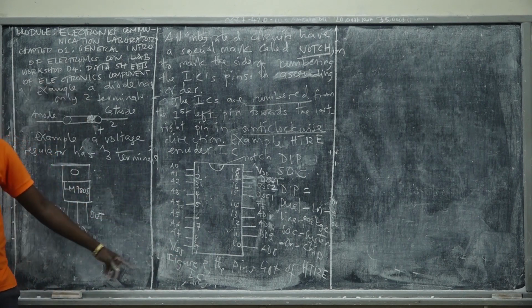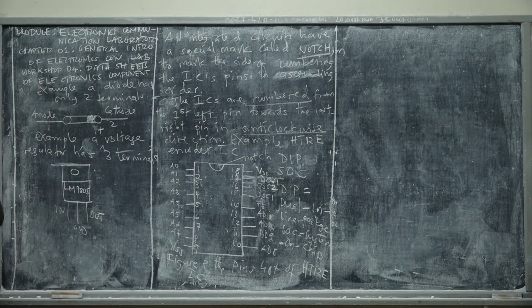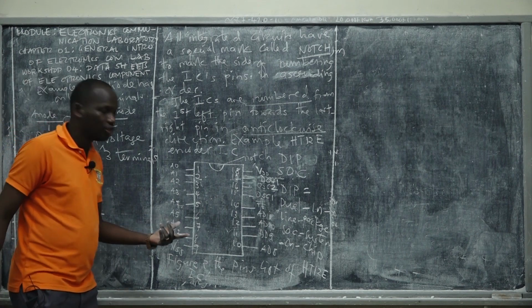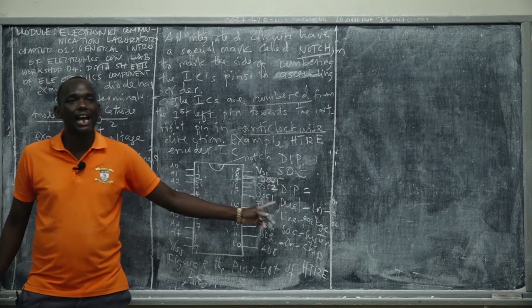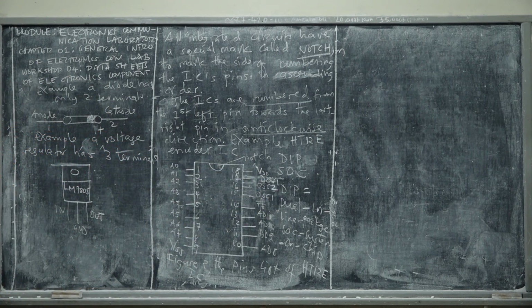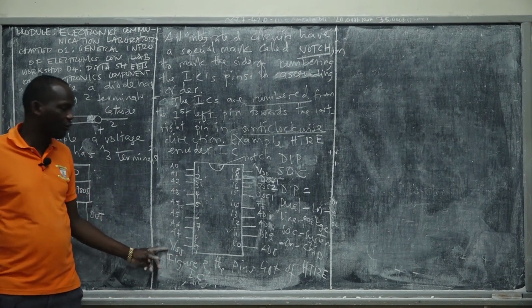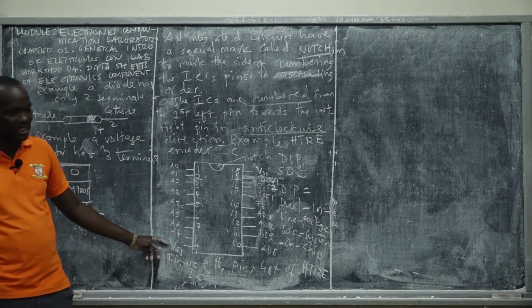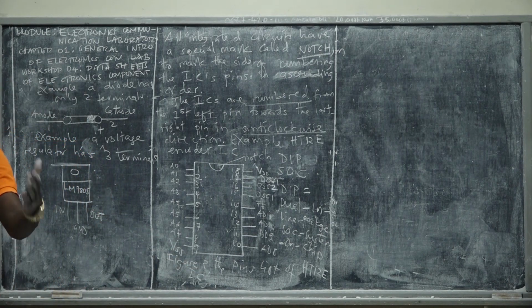Then VSS is the ground terminal. These are the abbreviations of voltage across source of the MOSFET transistor. SS means source. MOSFET has a gate terminal, source terminal, and drain terminal. So whenever you see voltage across source, you expect that the power pin will be voltage across drain, VDD. For a bipolar junction transistor, we have VEE, voltage across emitter. Then the corresponding power pin is VCC, voltage across collector.